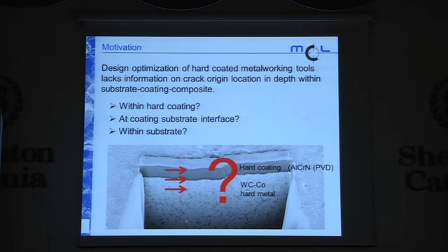They do initiate here. I can tell you hard coating people from Leoben also found that they may initiate within the coating, of course, or this is very likely to happen. But I'm also showing you today something about the interface or closed interfacial fracture that may occur in an aluminum chromium nitride coating that's applied with physical vapor deposition on a hard metal substrate.